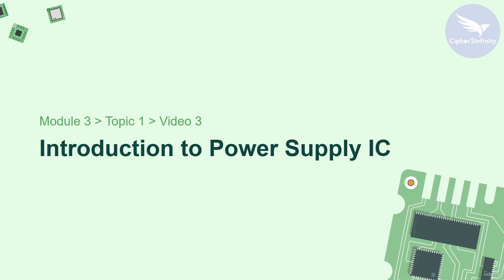Then the second conclusion was, as we are going to power our system using an external 12 volt adapter or external 12 volt power supply, that external adapter should be capable of providing 451 milliamps of current. Okay, so that was basically the second conclusion.